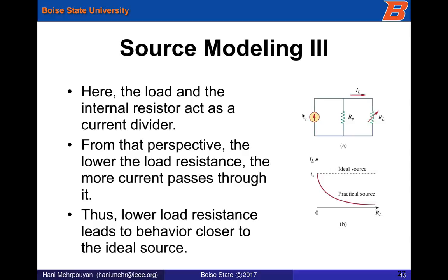But when we're looking at a voltage source, we would like a very large resistance to get closer and closer to that ideal behavior. Obviously, in a lot of cases, when you're looking at the outside world, you're looking at voltage sources, right? Your outlets are voltage sources, your batteries are all voltage sources. Current sources are mainly, as I mentioned before, found in the case of transistors.